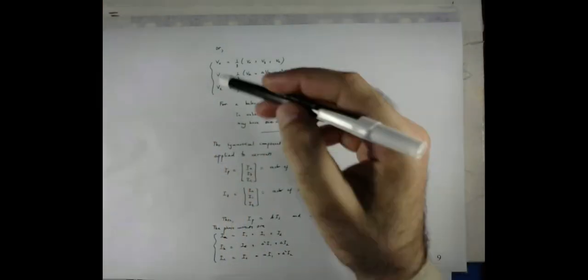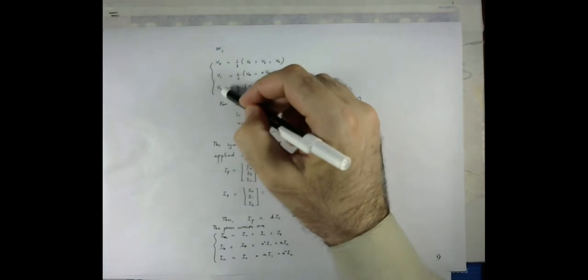If we have a negative sequence, like if the system is designed in such a way that after phase A we have phase B and then phase C, then it's a negative sequence, and obviously we will have only negative sequence voltage. These two will be 0. But in an unbalanced system, all three sequence voltages and correspondingly the currents may have certain values.